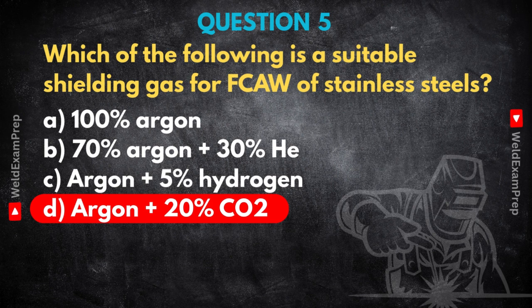But CO2 isn't bad for stainless in this amount. Doesn't it cause oxidation? That's the key, the amount. At 20%, it provides benefits without causing excessive oxidation or leading to significant carbide precipitation, which would hurt the corrosion resistance of the stainless steel. It's a carefully chosen balance.